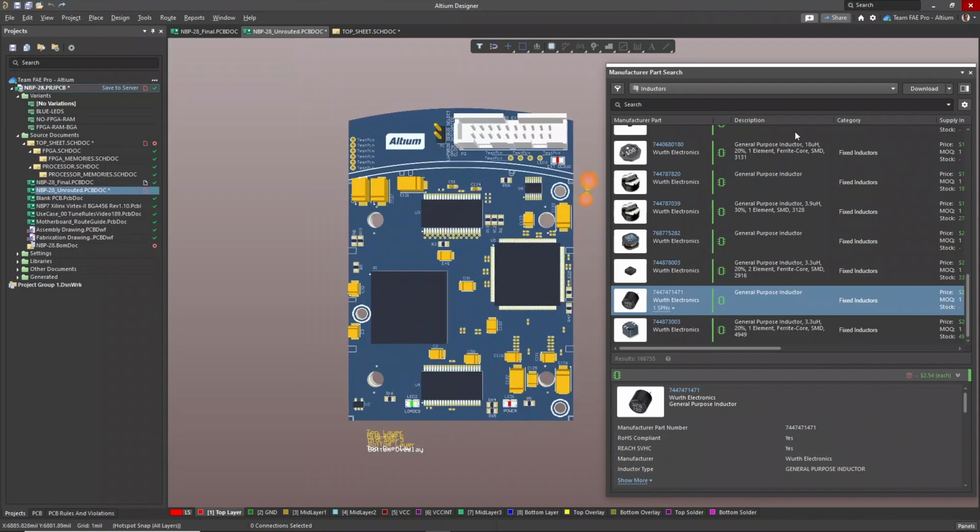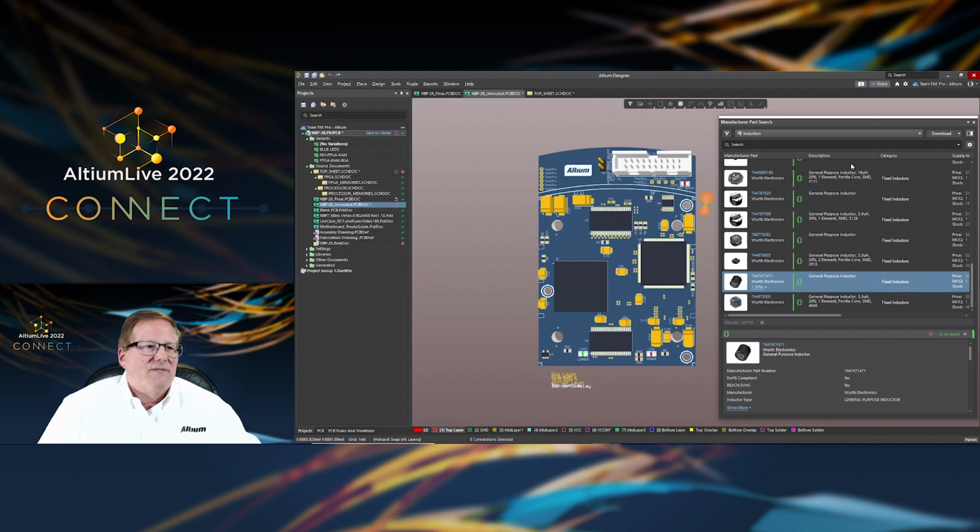So, the thing I wanted to get across is, with the manufacturer part search panel, you're able to filter, you're able to identify components. You can also do that extra due diligence, just like going back into an old data book and just dragging it right onto a board. I just dragged it right off of the component cloud onto the board to see if it would fit. I could very well have it in my enclosure and do my due diligence that way. You can place 2D to see if you have real estate available. I showed you how you can place the 3D.